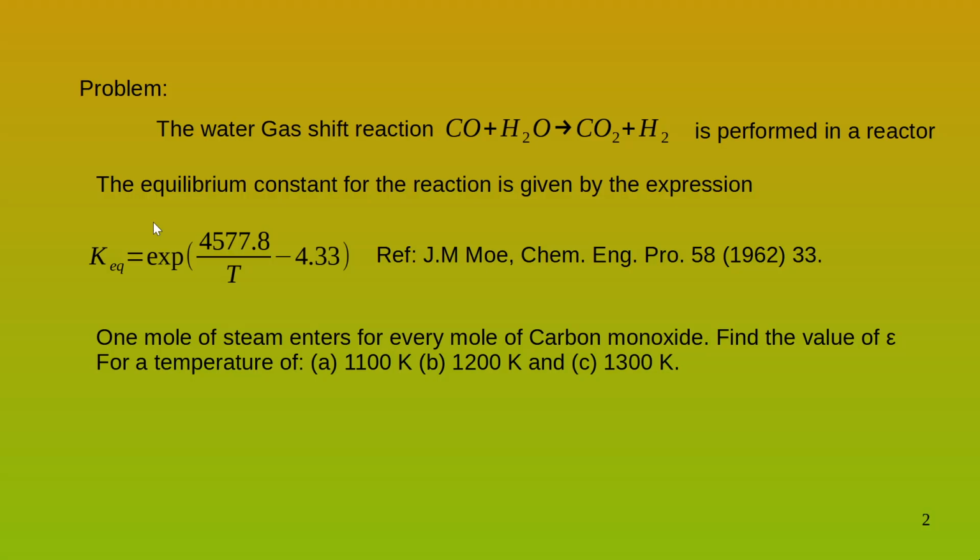However, one needs to understand, and I would like to make everybody aware, professional engineers as well as students, that K gives you only the equilibrium constant. But remember one thing, for any practical reactor, the equilibrium is never reached. Why? Because what is the time required to reach equilibrium? Well, it's infinite.